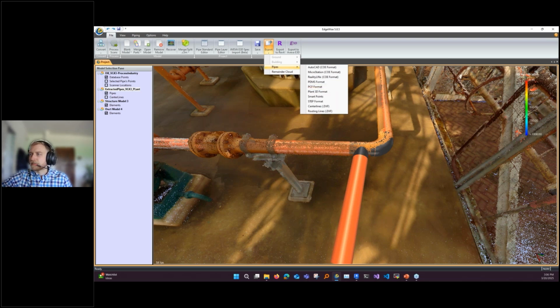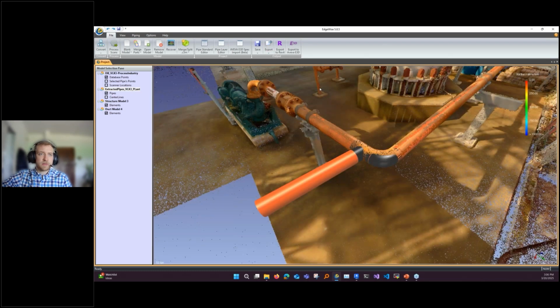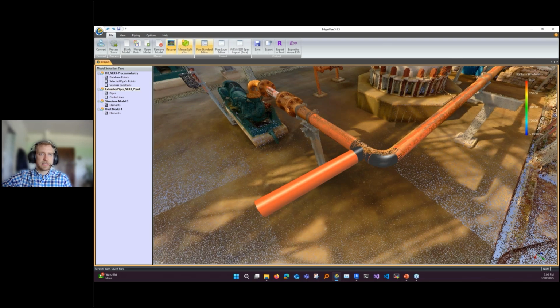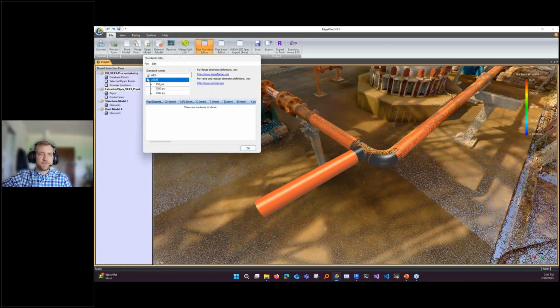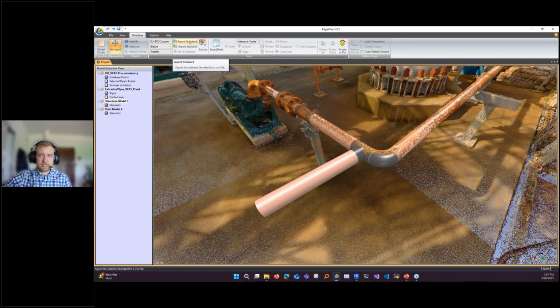Let's see. So standard sizes. The standards for piping are located in the file tab, and then it's the pipe standard editor, and you can see all the sizes there. It spans the table out for the different pressure ratings for those primary values. Structure is a little bit different. For structure we have an import standard. You would export one of the existing standards, modify it, and then import it back in. When you import it, it is saving it to your documents folder in an EdgeWise standards folder. But that's going to dictate all the different sizing and other information.